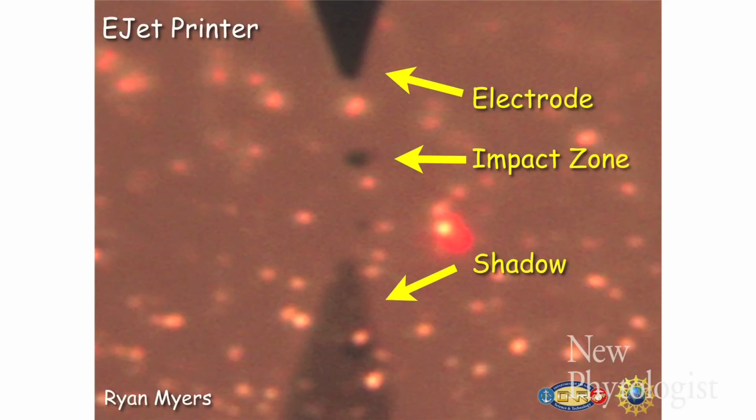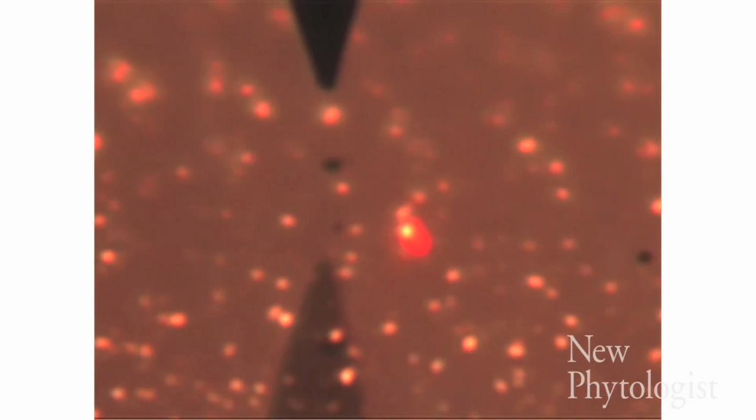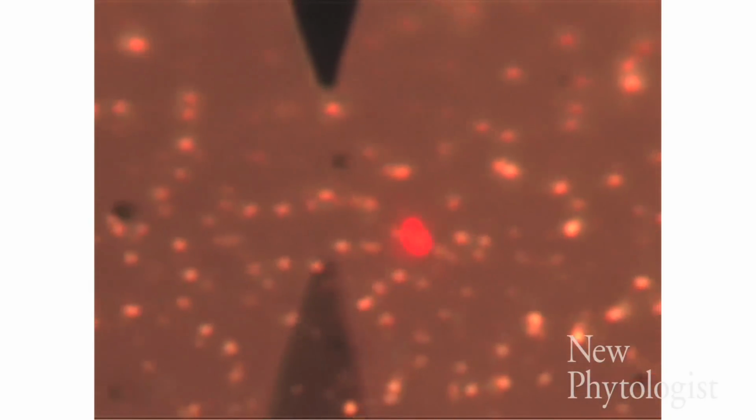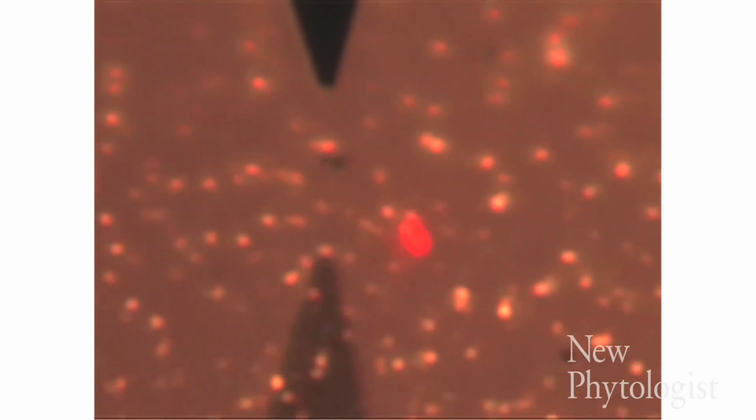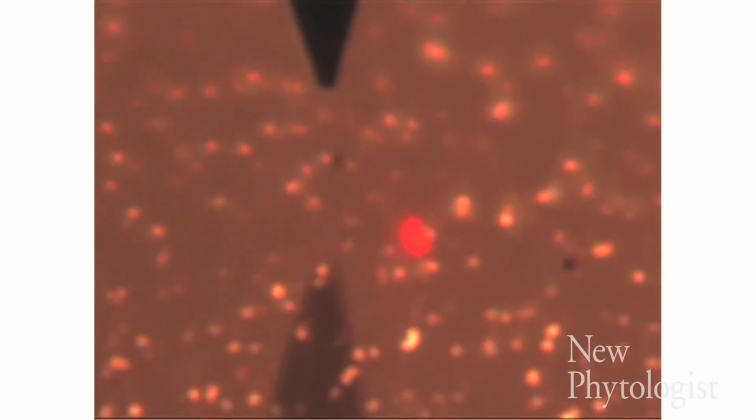And so the idea is the shadow of the microelectrode, the distance between the electrode tip and the shadow, tells you how far you're off the substrate. And these are little droplets of nanoparticles of gold and ethanol. And the ethanol evaporates almost immediately. And then you can make big splats to create pads for connecting wires. But we can produce extremely small patterns.